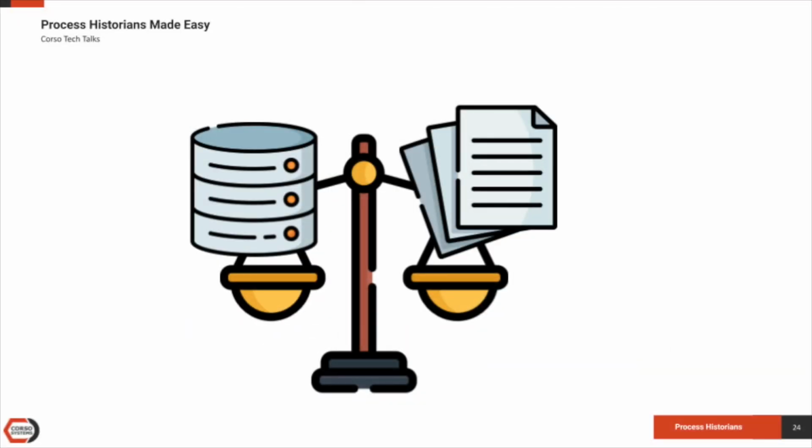Generally, choosing a historian is based on the cost versus benefit analysis. Adding an Ignition historian to an Ignition system can handle a large amount of data and is relatively cheap, whereas a purpose-built historian is usually licensed per tag. There are also resource costs involved in purpose-built historians in terms of training and maintenance to take into account. If you're well versed with SQL, getting a purpose-built historian might add some additional complexity to getting access to your data for reporting, for example.